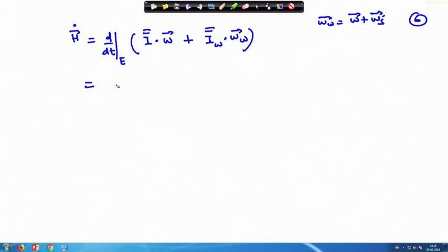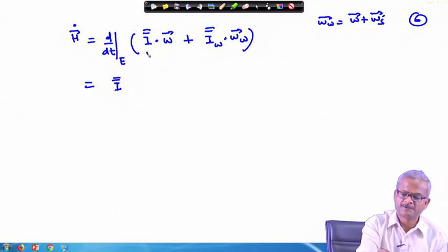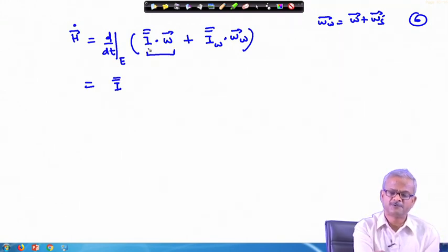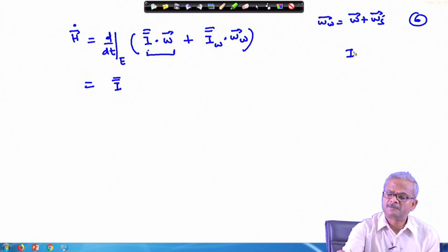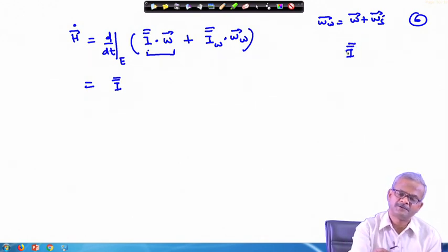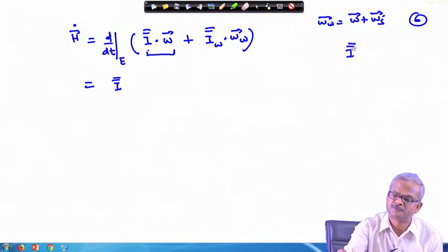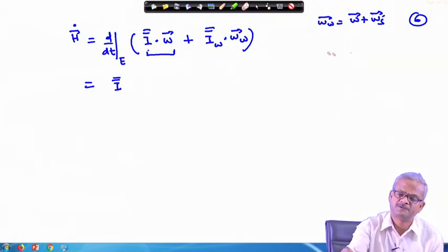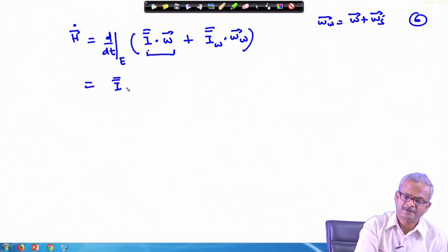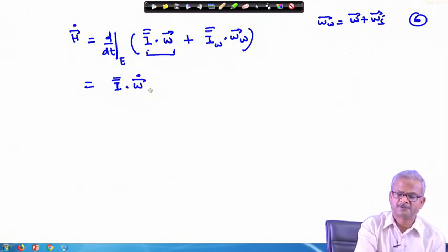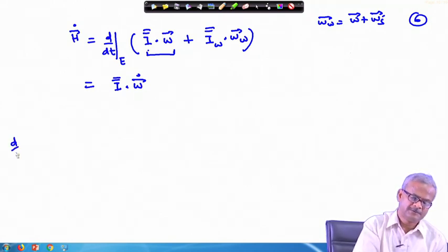So, once we differentiate this part as usual, and we are assuming that with the rotation of the wheel the I does not change. Once the CMG is working, in this part there is no question of that, because we are considering it separately. So, there is no need of that assumption. So, just remove this part. So, I times w dot, this is with respect to the body part, we can break this into d by dt with respect to the body axis.